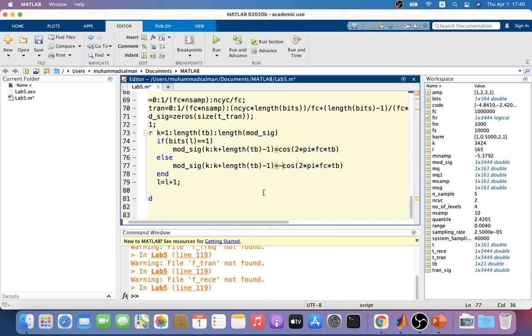There are different types of modulation schemes. For example, QAM. If it is 4-QAM, it means that you have four quadrants here, right? And each quadrant contains one constellation point of the signal. If it is 16-QAM, each quadrant contains 4 constellation points of your signal.